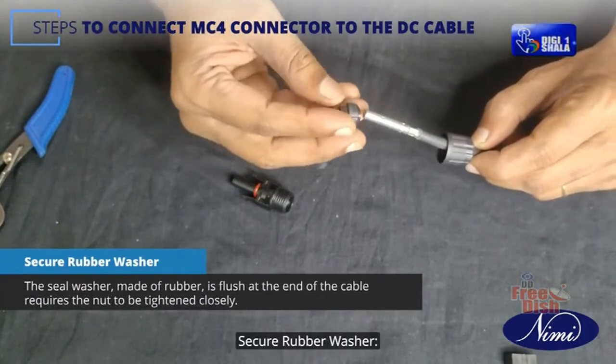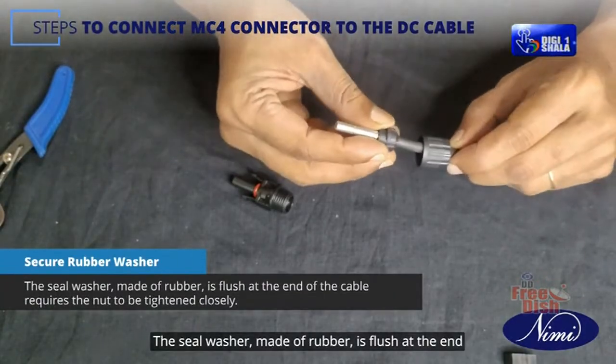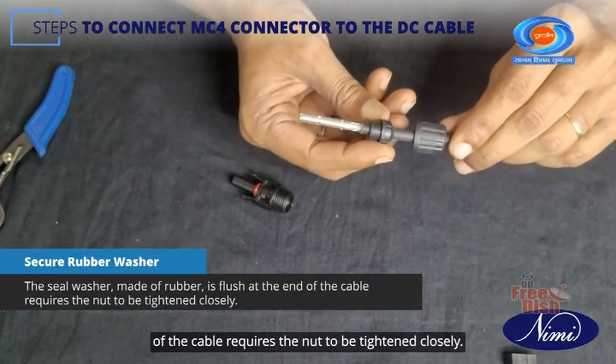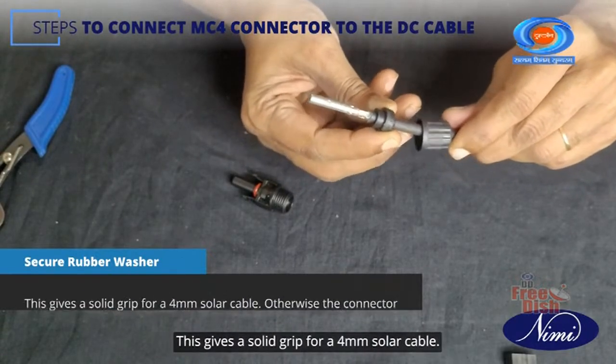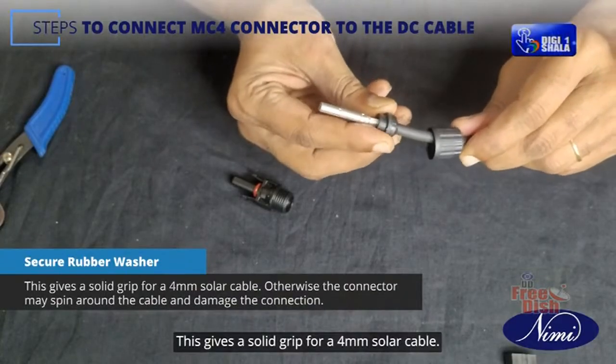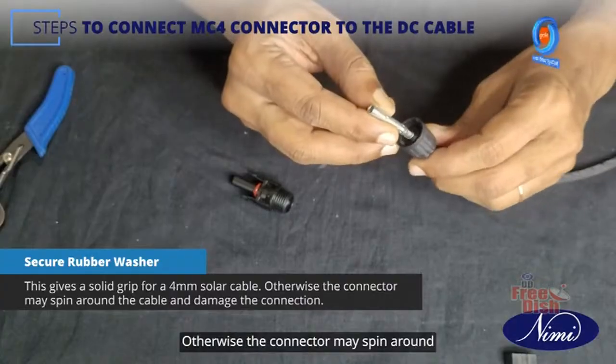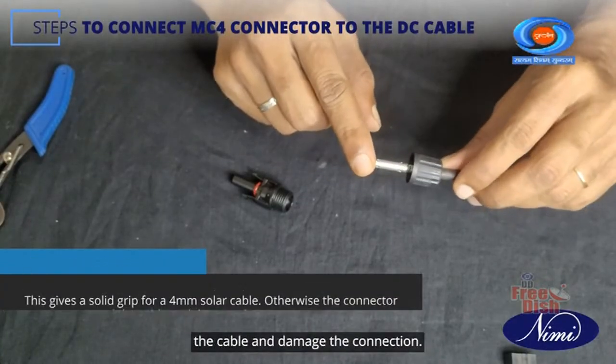Secure rubber washer. The seal washer, made of rubber, is flush at the end of the cable, and requires the nut to be tightened closely. This gives a solid grip for a 4 mm solar cable. Otherwise, the connector may spin around the cable and damage the connection.